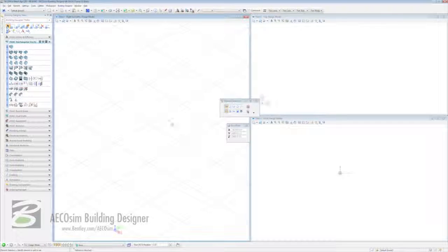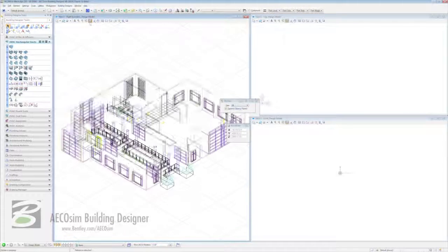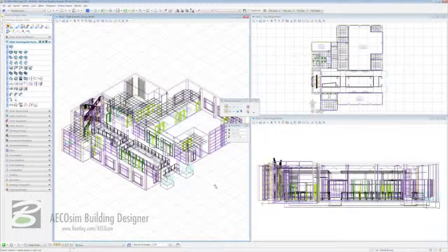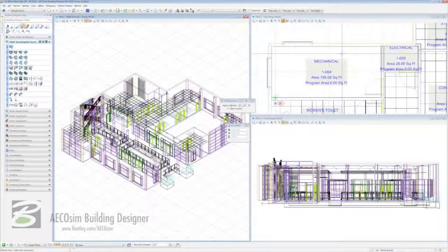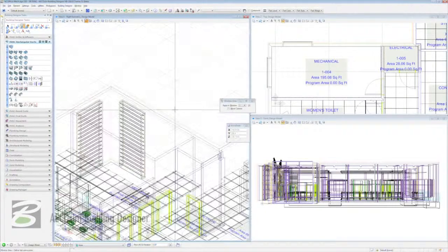We can also use a very handy icon and tool here in our view navigation. That is a fit view. We click in all 3 views, and straight away we see the extent of our model in the projections that we have set. The next step is to actually start placing our equipment, and we're going to start with an AHU. To begin with, I'm going to come into my View 2, to my window area, and I'm going to click once, twice, and zoom into our mechanical area. The same in our Right Isometric.